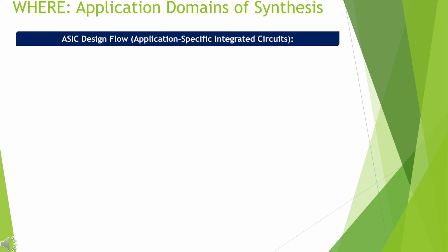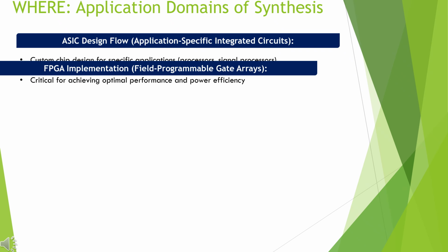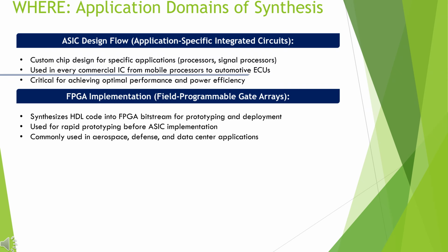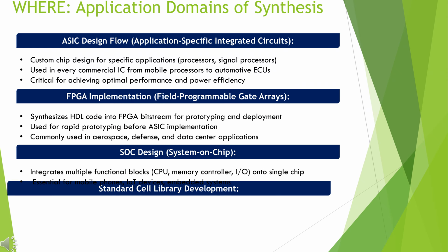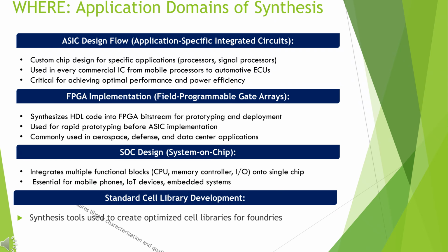Now, where does synthesis show up in the real industry world? Synthesis is used in ASIC design, FPGA implementation, SoC design, and even in standard cell library development. In ASIC design, every custom chip, like a processor or a controller, goes through synthesis to convert RTL into gates.